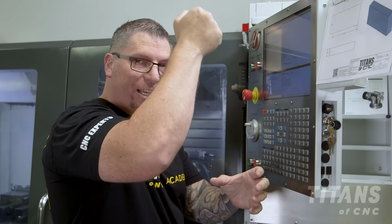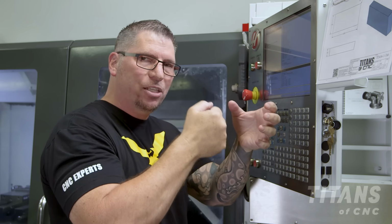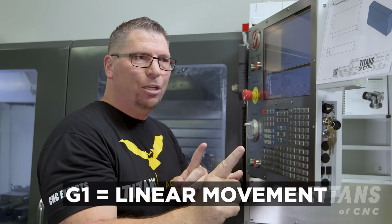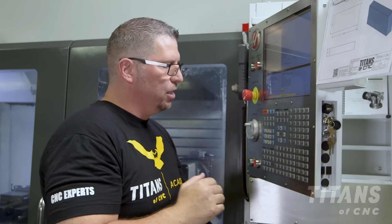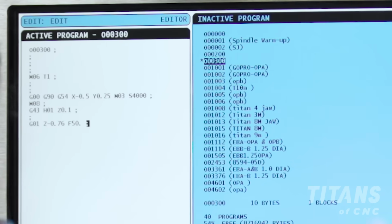So when we're above, we can rapid G0, we can move around, we're not gonna hit anything. But now we're gonna actually submerge, we're gonna drop down and engage the material. So I'm gonna go from a G0 to a G1. A G1 is a linear movement with a feed rate. So my part is 750 thick, so I'm gonna drop to Z negative 760. So I'm gonna hit G1, Z negative 0.760, feed 50, enter, and I'm down.